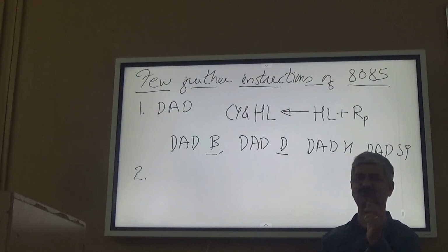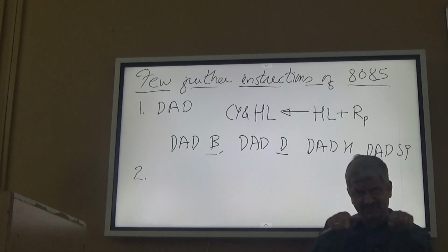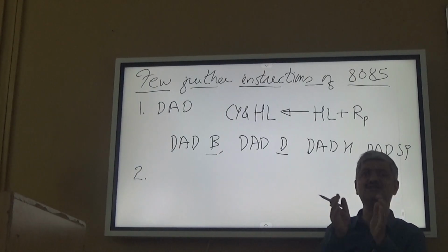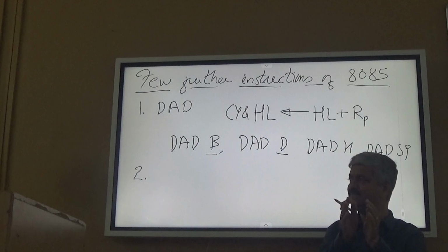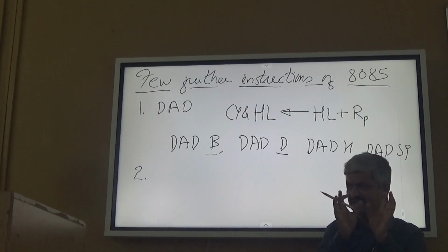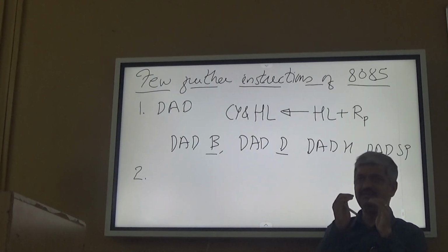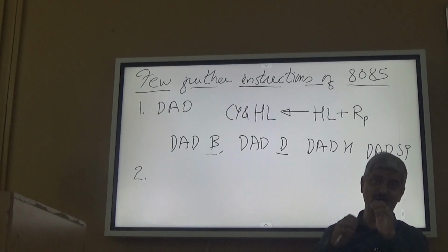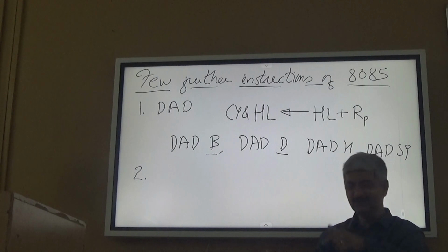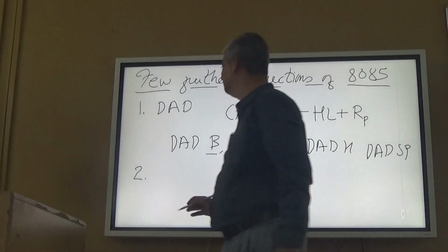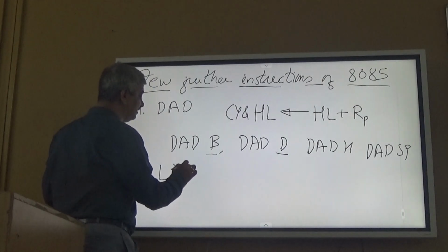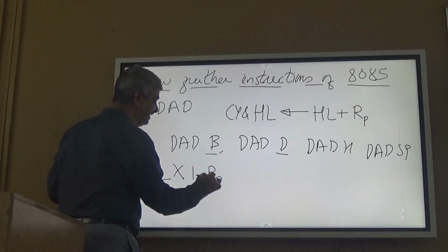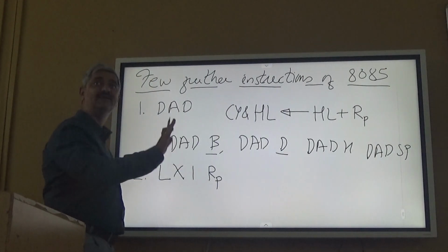Merely because some space was available in the design of the instruction set, and to make things somewhat simpler, the register pairs BC, DE and HL are also allowed to be initialized as a pair. It doesn't bring much value, only 1 byte is reduced while programming. For SP it must be there because it is individually not accessible. So there are a few instructions, LXI, load register pair.